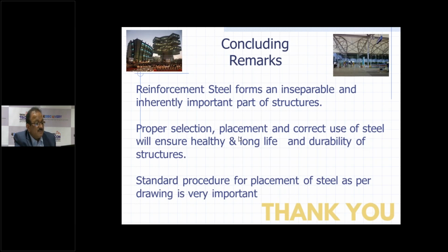Then Hemant Odalkar is asking, we should go with stainless steel reinforcement, which has a lower life cycle cost for the structure, but it is very expensive. Some structures have tried this, a few sites just as an R&D matter. Commercially it's not viable. If you have a lot of money and you don't care for the expenses, I don't mind you going for stainless steel reinforcement bar.